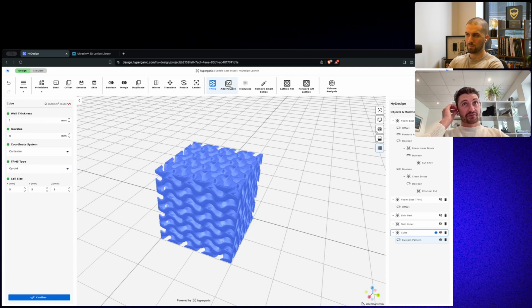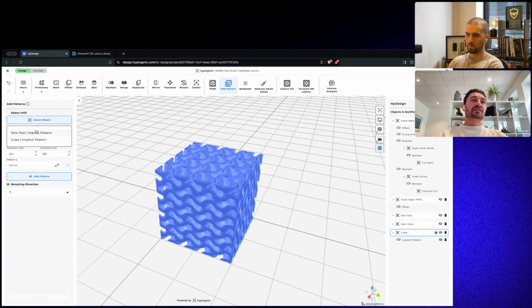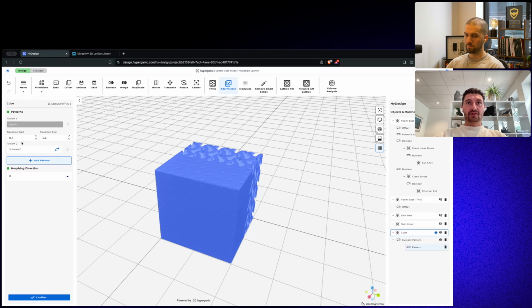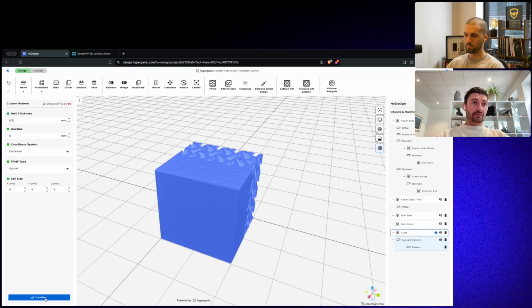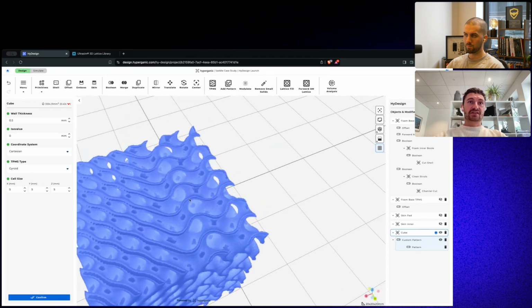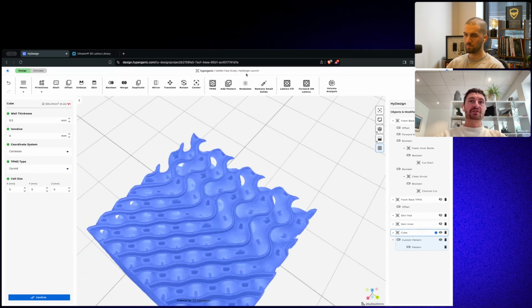Now to illustrate some of the functionality that is available to the user, such as the infills here, you can merge one pattern, which is here a gyroid, into a second pattern along a primary axis. In this case, I'm going to merge this into a Schwarz diamond along the x-axis. Confirm this quickly. Maybe increase the wall thickness slightly, or decrease. That should do it, and open up the structure. Very nice. You can see that there's a smooth blend between these structures.